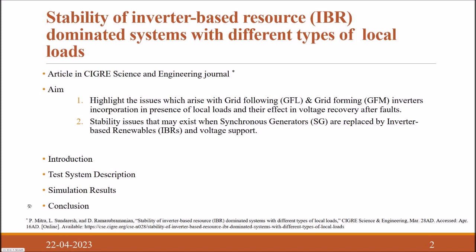There are two aims of this article. One is to highlight the issues which arise when grid following and grid forming inverters are incorporated in the power system in the presence of local loads, and their effect on voltage recovery after faults. And second, this article investigates the stability issues which may exist when synchronous generators are replaced by inverter based renewables.